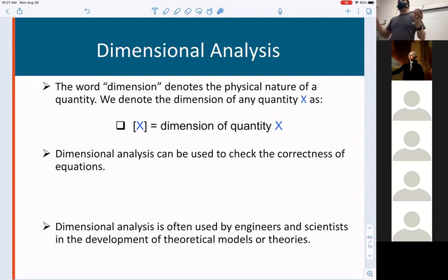And then you want to see if you can build a model for the flow rate. You might try to build a model saying, well, the tank has some volume, the tank has some area, it has some density of material. So you can write down all these different things that the system depends upon. And you could try to build something that has dimensions of flow rate. That can be your first guess in trying to determine it; you probably have other physics principles and engineering principles you will apply. But you can imagine that you're working on a system where you don't know much about it. Often a first attempt is to build something out of quantities that the system depends on that has the right units for the thing you're trying to describe. And then you put in some parameters and you try to fit it and see if it gives you a good description.